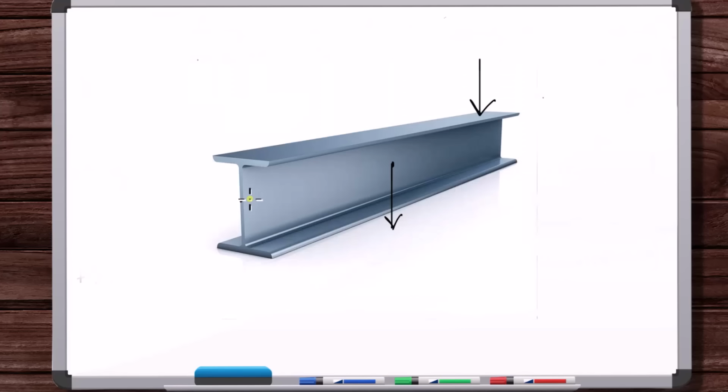You could do that. But coming back to this beam here, so in statics, in this introductory course, anytime we make a cut, we're going to assume that we have a pressure distribution that has resultant forces at the centroid of the area of that cut. Now, usually it's going to be an unknown force, and with unknown forces you can put them in any direction, right? The sense doesn't matter.